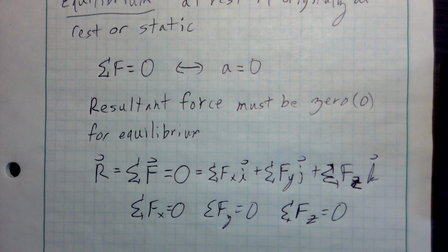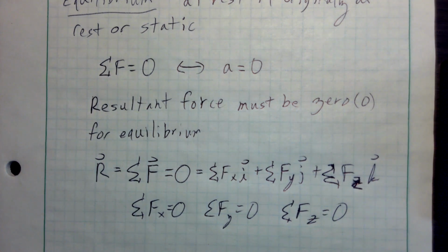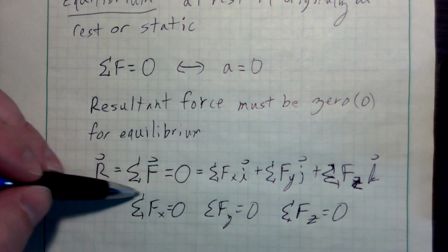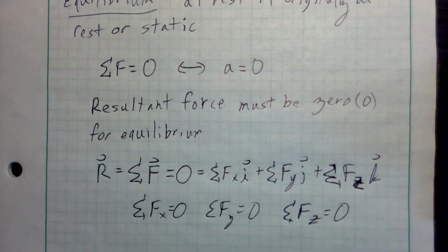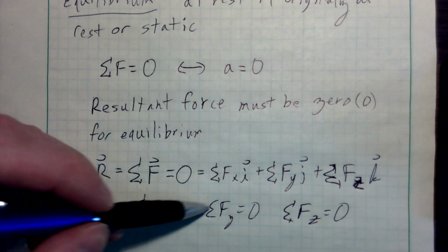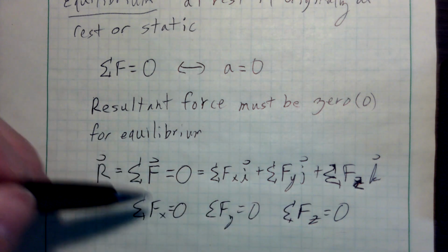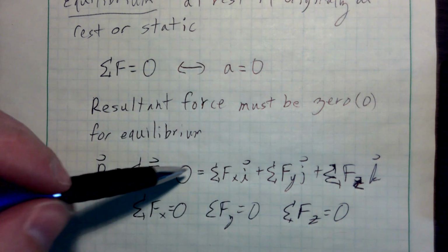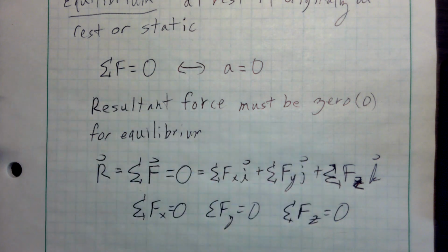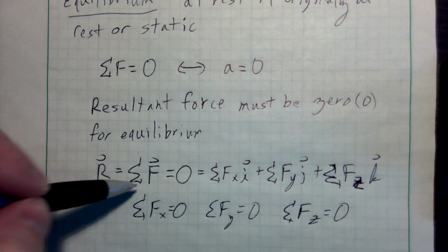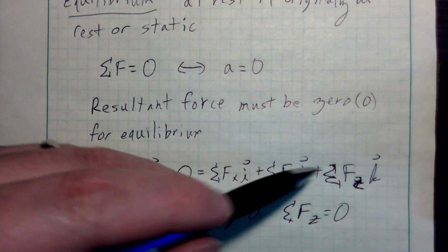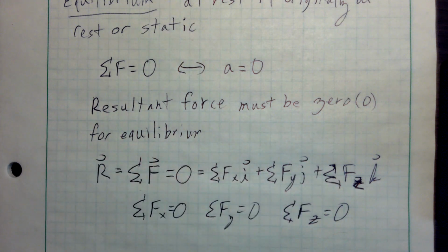My statics professor used to joke that statics is super simple because there's really only one equation, and that's true. This is really the main equation. There are more than that, but you can see in 3 dimensions this equation splits out into 3 different equations. This one vector equation, when we look at the different components of that vector, says if I add up the total forces, the net force vector must be 0. That means the force in all 3 directions must be 0. And in a 2D problem, this one goes away. I'm just dealing with x and y, which is what we'll start with.